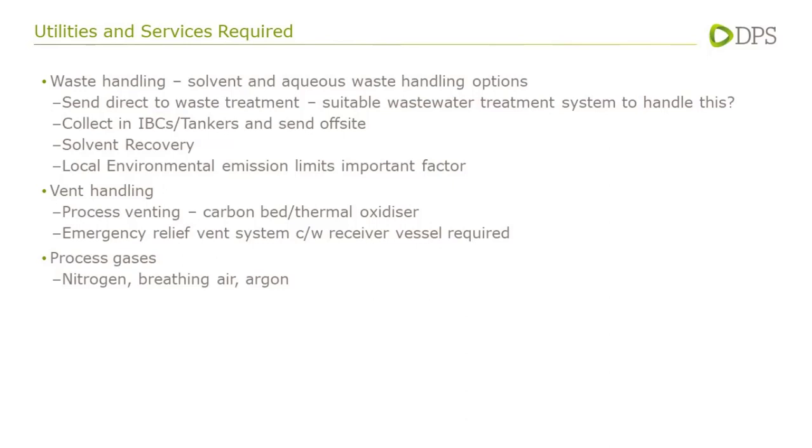If off-site disposal or on-site incineration is required, a plan must also be in place for this. Waste storage, tankering, etc. Considerations must also be given to aqueous waste streams containing high COD solvent levels. Ultimately, the local environmental legislation and emission limits will determine the level of capital cost required here.